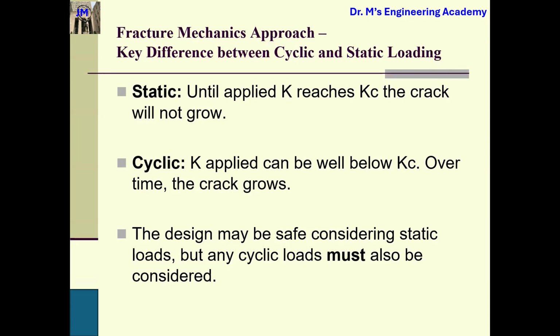Stress intensity factors. So N is a safety factor or design factor. It is usually greater than 1.0. So we use this equation to check whether we reach the critical state or not. So this is for the static loading.